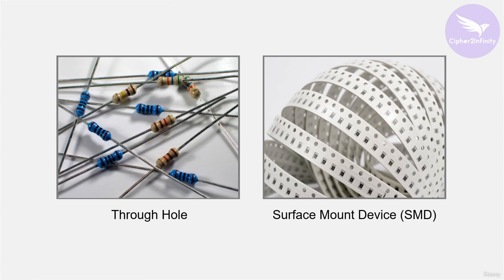And from a price point of view, both of them have a similar price. But as you know, in the case of a through-hole resistor, its size is big, so it's obvious that it's going to take more space on the PCB. If we consider space as an aspect, then through-hole resistors are actually more expensive, because they take more space on the PCB, which results in a larger PCB and, as a result, an increase in price. So through-hole resistors indirectly increase the price of the product.